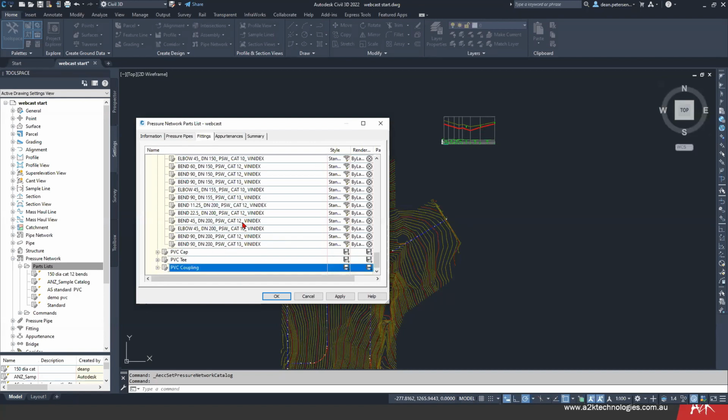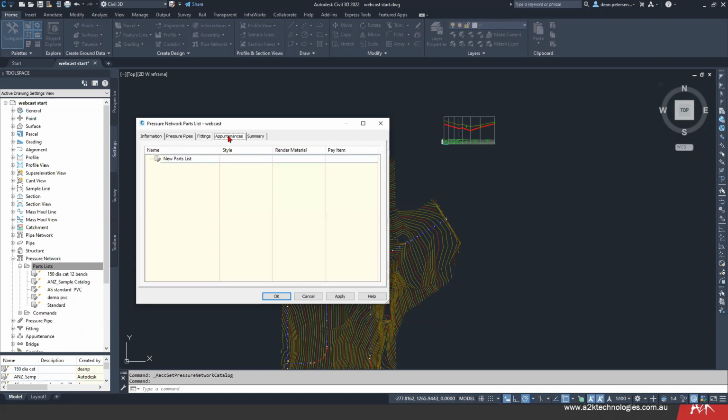The other ones you don't need to change, so it will select the sizes that you want. Now, one thing that we don't have is the appurtenances from Plant 3D. These did not convert from Plant 3D, so these are things like your valves, etc. You can, however, mix and match this catalogue and the default catalogues that come with Civil 3D, which means that you can grab an appurtenance from another catalogue and put it into the same network as what you're laying out.